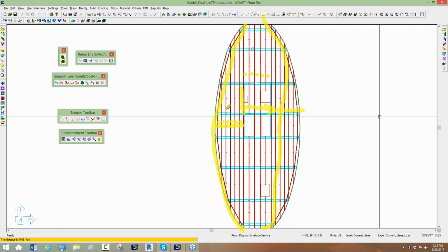And so I keep my spacing as is, I keep it set. And then if I find that I need to add more force or more tendons necessary to meet, let's say, allowable stresses or pre-compression or whatever it is, I can slide or reduce the number of cables at that spacing increment.